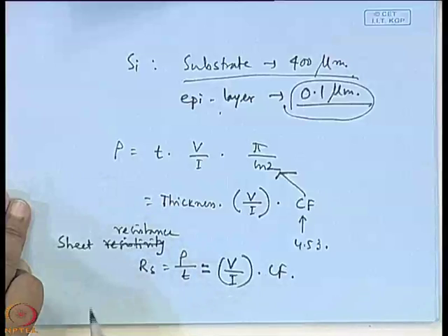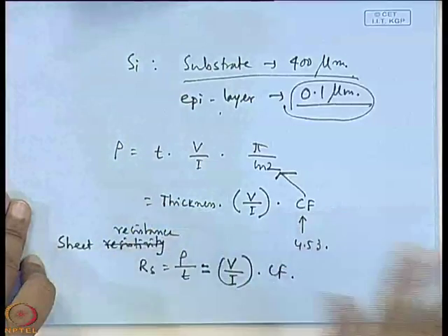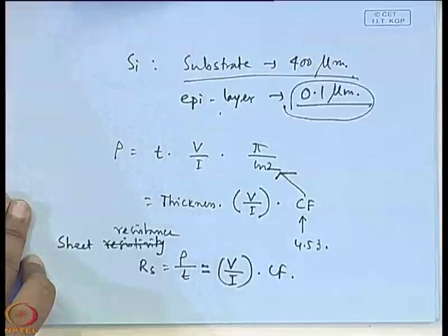Now, why have we calculated the sheet resistance? Because it is a thin sheet. So, we can characterize that thin sheet with sheet resistance or the sheet carrier density.